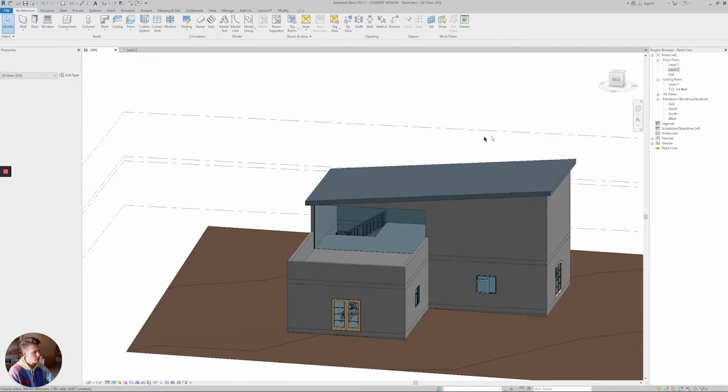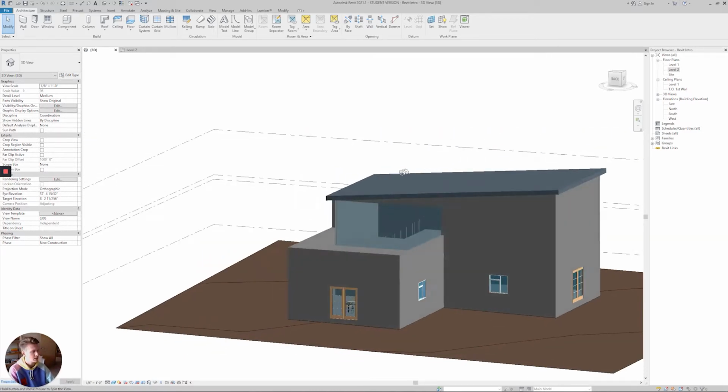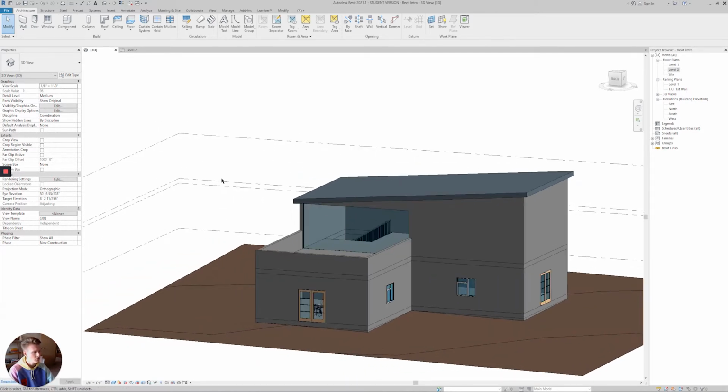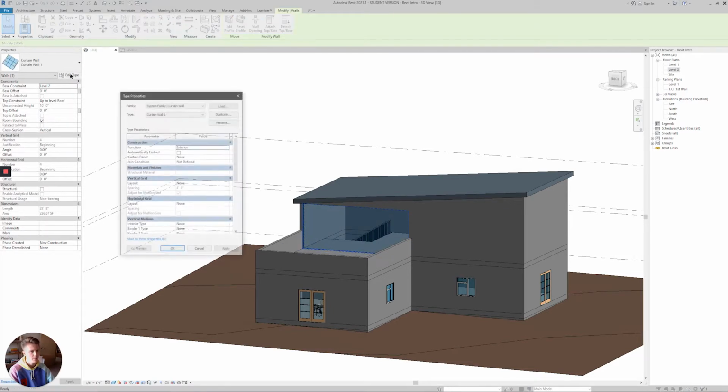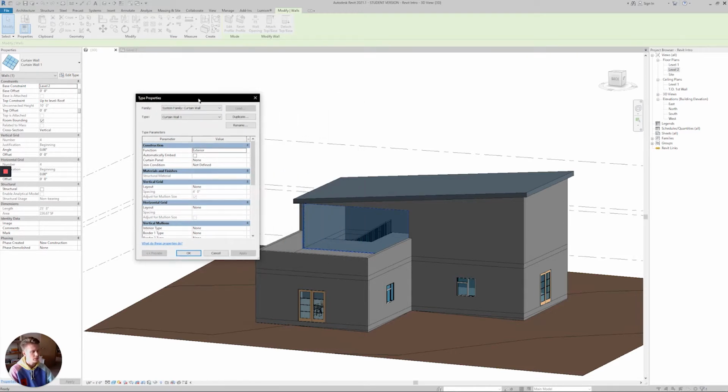And you'll notice that this is just one single glass sheet, and most curtain walls, like at your house, you'll notice that they have aluminum grids going through them to frame each individual glass panel, because realistically manufacturers don't make glass panels this large. So to make that the way we want it to be, I'm going to select the wall, go to Edit Type in the Properties tab, and it'll bring up these options for me, and you'll see vertical grid and horizontal grid, and that's what I want to edit to add these grids.